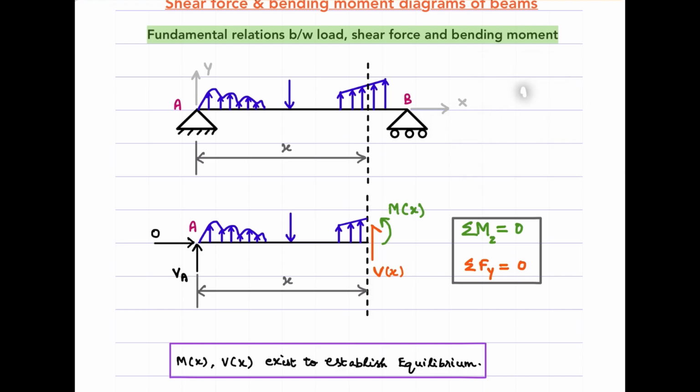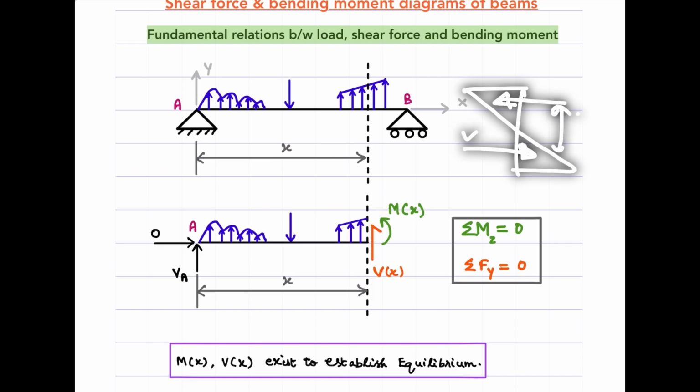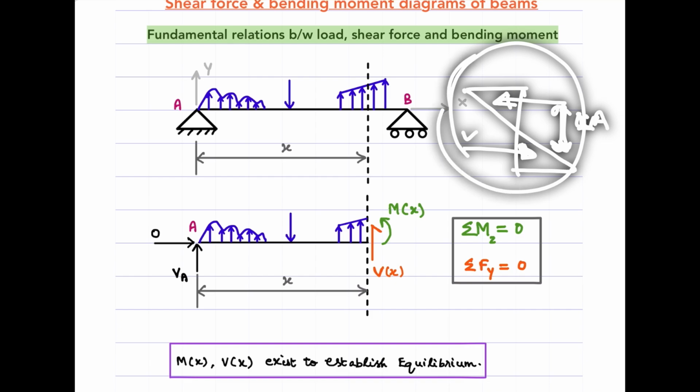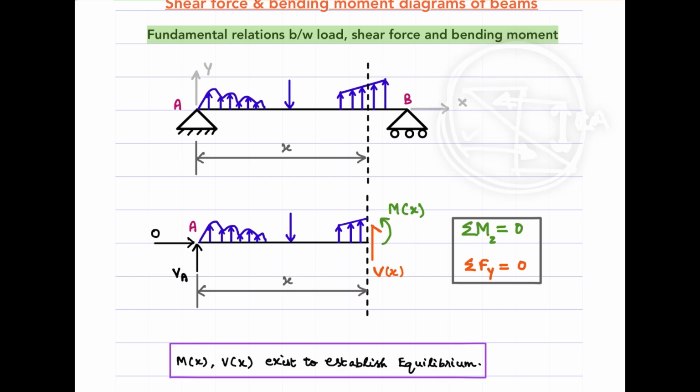Now what one can do is, in the stress profile, replace the top distribution with the resultant like this, and the bottom one with the resultant like this. These are LA distance away from each other, right? Where LA is the lever arm. So this constitutes what? A couple, which is the resistance offered by the beam. And that is called the bending moment, right? It literally bends the beam and hence we call it the bending moment.